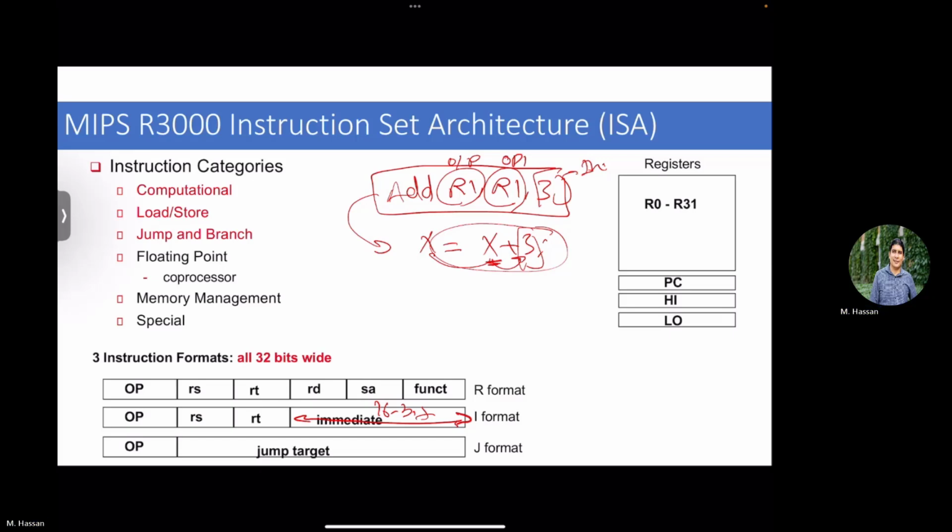Right? Then finally, there is a very special type of instruction that will come up a lot in this course because there are a lot of headaches later on also in the jumps or branches, right? The jumps. Things we discussed in the first lecture: you have a for loop, an if condition, a function call. So you need to jump to an address. So these are the jump or branch instructions, and they have the J format.